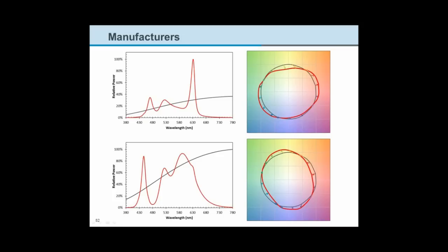I can see on the icon here that one of those is essentially saturating the greens and desaturating reds. It's going to lead to a higher luminous efficacy of radiation, so a higher potential efficiency for that spectral power distribution. But if we look at the top one, it might have a lower LER, but it's increasing reds, which, if anyone is familiar with R9, reds are very sensitive to us, and so increasing that saturation might actually be the preferred source. So these are the trade-offs that manufacturers are going to have to discuss and go through, and really use these new tools to make those decisions more appropriately.